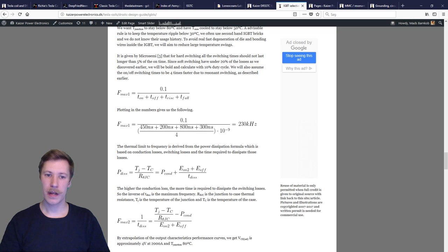I calculate with a 30-degree temperature rise, and this is for a single pulse, that the die inside the IGBT is allowed to rise from, let's say, 50 degrees Celsius to 80 degrees Celsius. Then we have to give it enough time or conduct a small amount of power that it can cool off back to 50 degrees before we try to switch a large current once again.